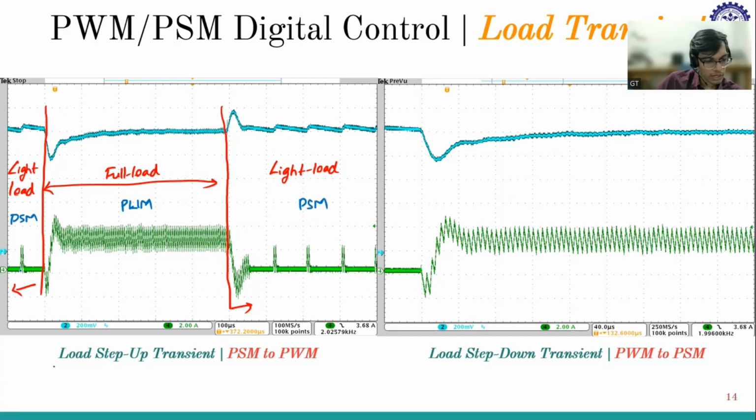So what is happening? Here it is a fixed pulse followed by charge pulse, skip pulse, charge pulse, skip pulse. I think there are two charge pulses. So these are charge pulses. And these are skip pulses, depending upon how much it is getting charged. So it again depends upon the duty ratio. We have seen how duty ratio will affect and different types of case studies we have discussed earlier.